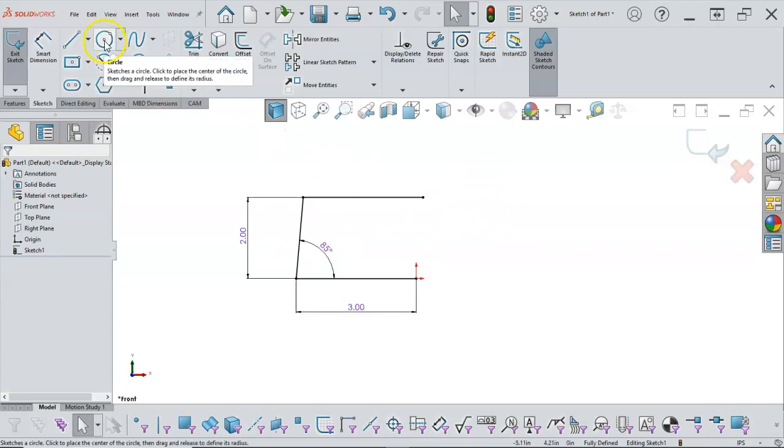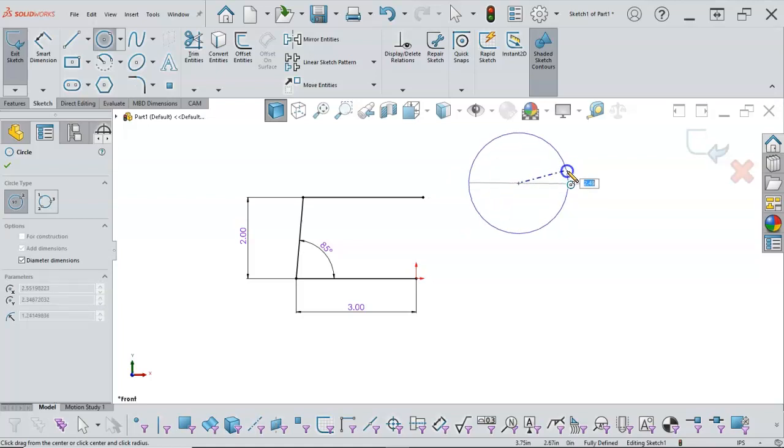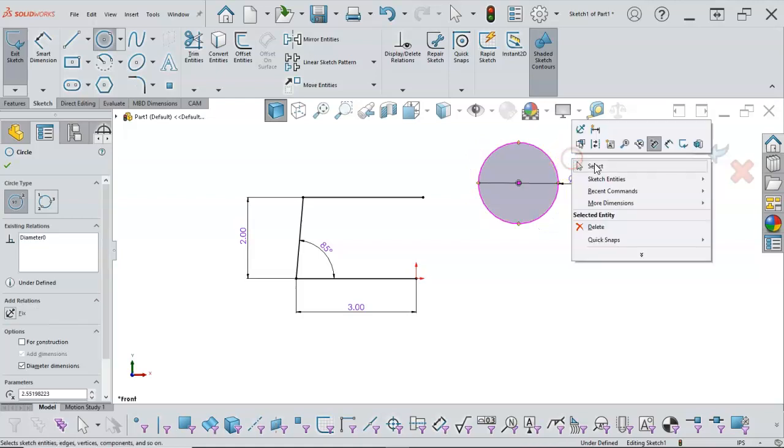Let's go ahead and look at the circle. And we have the circle and the perimeter circle. So a circle is going to be, if I do the click and drag, and I'm going to try to keep it from inferring anything so that I don't end up with any extra. So as I'm drawing the objects, the sketch numeric input will go 2 inches. When I hit enter, it completes it for me.